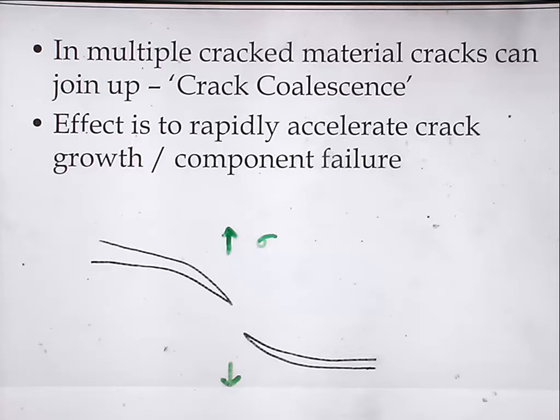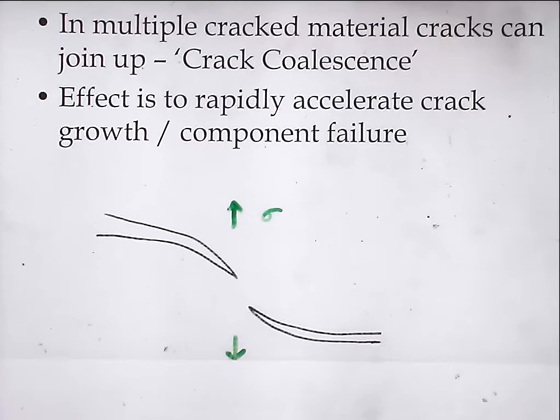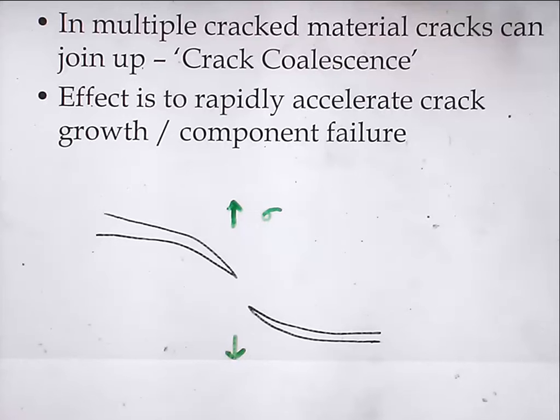The next time we'll talk a little bit about looking at the dissolution rate, and that gives you an idea of how to calculate the rate of growth of the crack. But as soon as they join together and you start doubling the rate, you start getting this exponential growth, it gets out of control. I thought what I should do is show you some fracture surfaces, in case you haven't seen any at all. Hopefully some of you have seen some fracture surfaces.